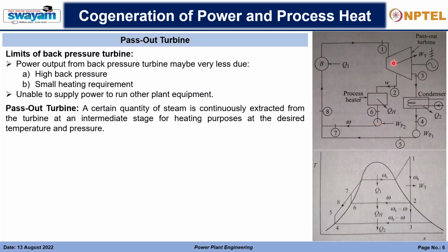Then the steam which has already expanded to the full capacity, we are not inducing any back pressure, we are not limiting the exit conditions, so that will be going to the condenser, and the heat will be rejected to the condenser, and from there to the pump, and the pump will be delivering it back to the boiler. So that is the whole case. Okay, there is one more case in that I will be speaking of, but till now this is the case. So in a TS diagram it looks like this.